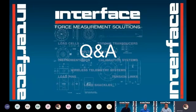Very good question. And as they say, the devil's in the details. But these are very stiff. All of our multi-axis sensors are quite stiff, which means they react to impacts as well as any of our sensors do. And many customers do use our low-profile load cells and others in impact testing. That said, impacts can create large loading conditions, and so you have to be careful of the survivability of the sensor. Also, there's a limit. They can only react so fast, but it's down in the millisecond range, typically.